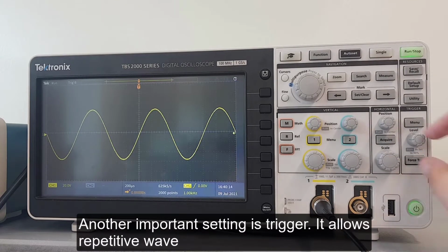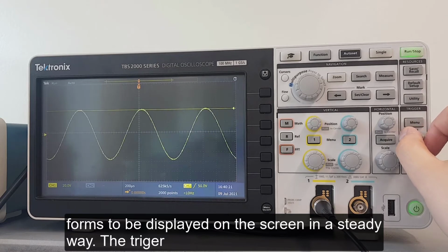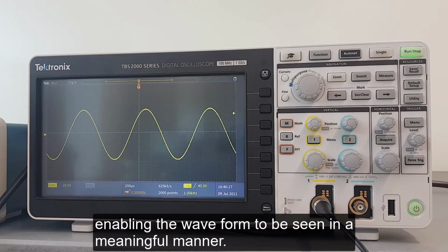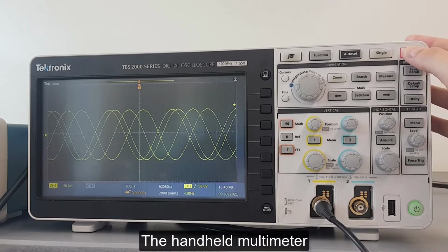Another important setting is triggering. It allows repetitive waveforms to be displayed on the screen in a steady way. The trigger synchronises the voltage and the time data of the waveform, enabling the waveform to be seen in a meaningful manner. Also, if the signal is noisy, you can stop the image to be able to observe it closely.